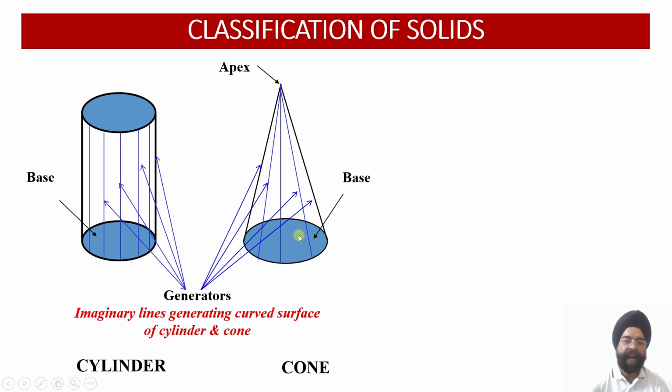So the larger the number of parts in which you are going to divide your cone or a cylinder, the more will be the accuracy of the surface or the shape which you are going to generate. So we can divide our circle or our cone into 8 or 12 equal parts. In case of your cylinder, there will be vertical artificial generators. In case of cone, there will be the artificial slant generators over there.